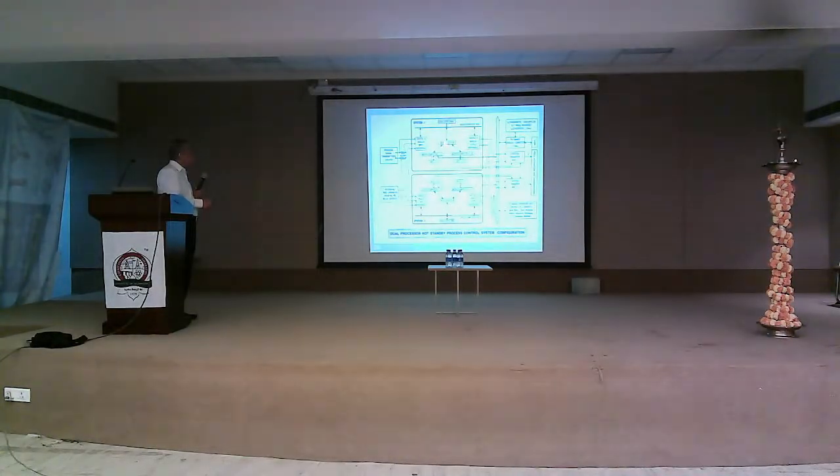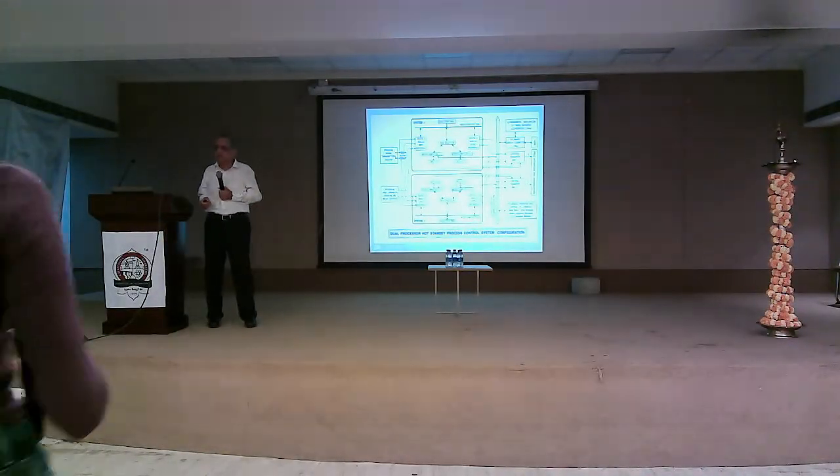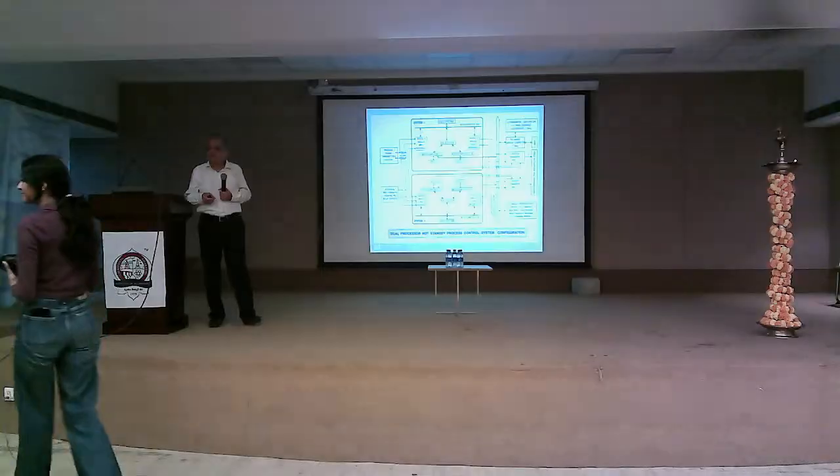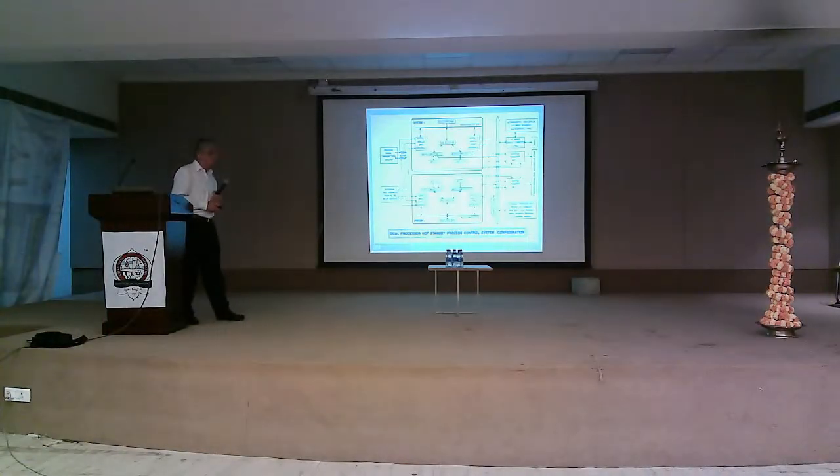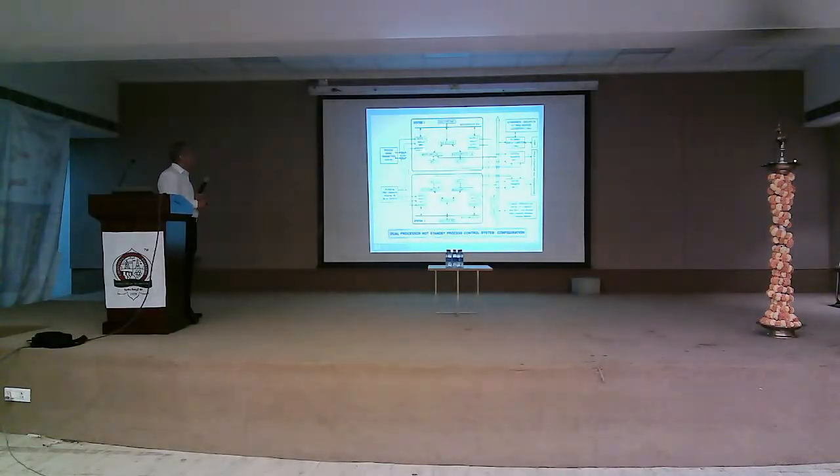After that, microcomputer 1B will also read all the inputs, calculate its output and write it in a dual port. Now, microcomputer 1A will compare its output with microcomputer 1B, and 1B will also compare with its. If any of these microcomputers finds that outputs are not matching for two cycles, then it is taken as a problem with the part and it is declared.